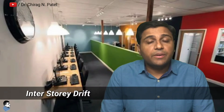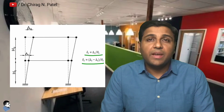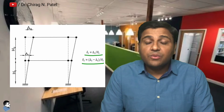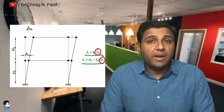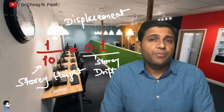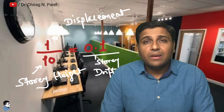Now if we talk about the interstory drift, it is the difference between the roof and floor displacements of any given story as a building sways during the earthquake, normalized by the story height. For example, if we take a 10 feet high story, an interstory drift of 0.10 indicates that the roof is displaced 1 foot in relation to the floor below.